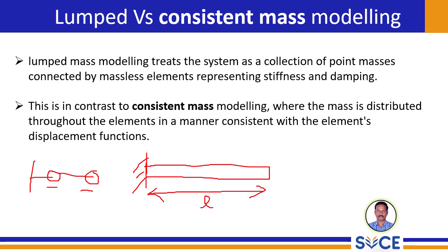In finite element analysis, a lumped mass matrix means we might place half of the mass at each of the nodes at the end of the beam. That is, for a simply supported beam, we place the mass at the ends of the beam. In the consistent mass model, as usual, mass is distributed all along the length of the beam. The mass matrix will have terms that account for how the inertia of one part of the beam affects the inertia of the other parts.